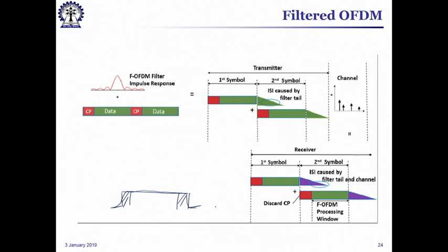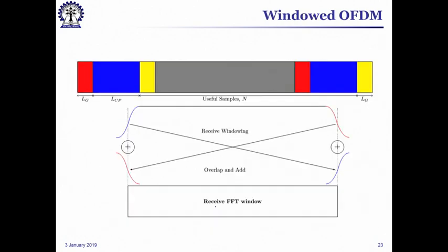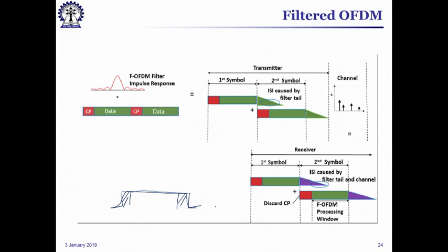So, although these have been proposed in literature as separate techniques, those are all pretty similar to OFDM and minor variations or probably more realistic implementations of things, especially the windowed OFDM. But when we talked about filtered OFDM, this is again a slight variation where you do time domain filtering, which is equivalent to having a window in the frequency domain. So, these are duals of each other. In one case you do windowing in time, and which appears as filtering in frequency. The other case is filtering in time, which appears as windowing in frequency.